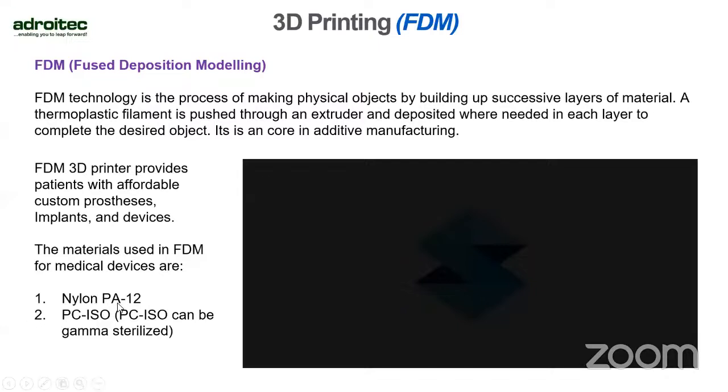And there are two materials in FDM which are very good for medical devices. One is nylon PA12, one is polycarbonate, which is an ISO certified material that we can use for gamma sterilized things, and it is a biocompatible material for developing medical devices or bone anatomy models, pathologies, or for developing medical devices like microscopes, telescopes, etc. In the next slide we will discuss a use case study.